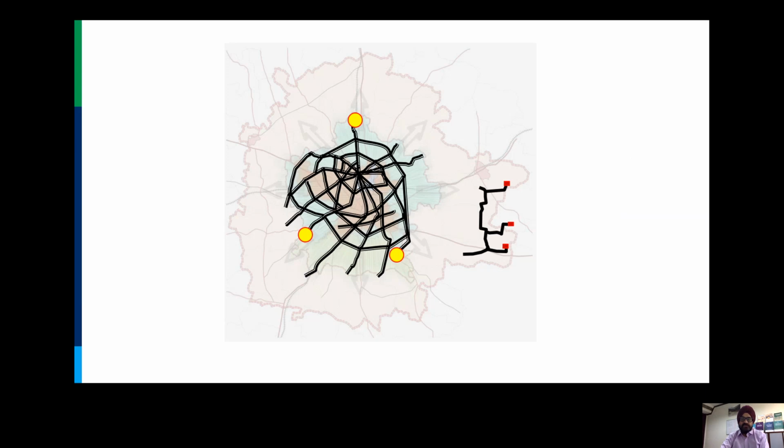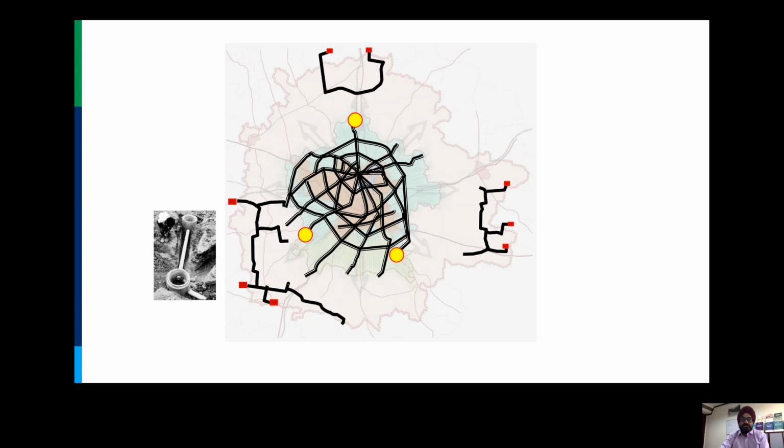Instead, we had various other types of sewage systems or just a drainage system in other parts of the peri-urban parts of the city. And this usually was just draining out into some stream. And later on, so what are the options now being presented? So you can have these shallow sewers which connect with your STPs, like those three dots would have been the STPs earlier on.